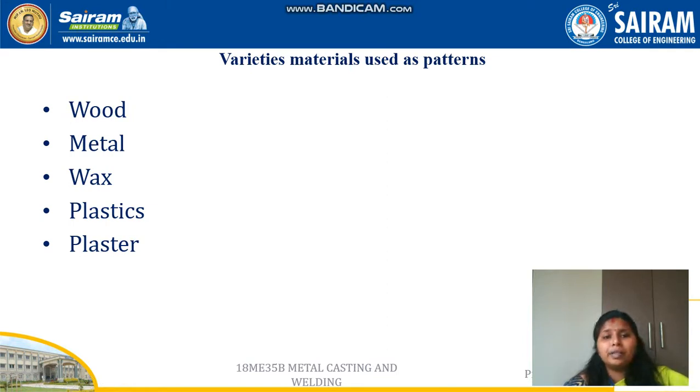For wood, there are plenty of woods available, of which pine wood, teak wood, and compressed plywood are generally used. For metal, there are aluminium alloys, steel, etc., which are commonly used for making patterns. The next one is wax. Wax is a reusable material which is light in weight. It gives us good surface finish and is also suitable for complex shapes.